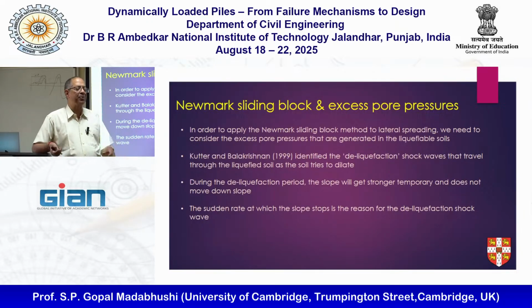You can't map everything just based on stress. You have to worry about the third dimension, which is the change in void ratio, or in Cambridge we call it specific volume. It's the same thing. Okay, so q, p dashed, and v is the 3D space you've got to work in, and this is another classic example of that.